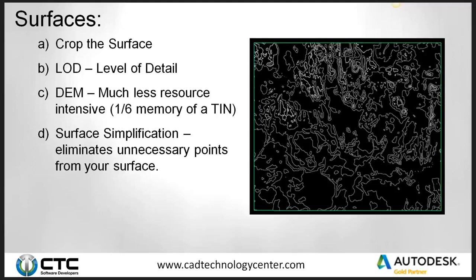It's not going to modify anything. So as we know, a 3 million point surface is going to take longer to regenerate than a 2,000 point surface. Even if it's the same surface area, that 2,000 points is going to work much faster because the triangles on your tin are a little bit larger and it has less things to think about to reprocess.